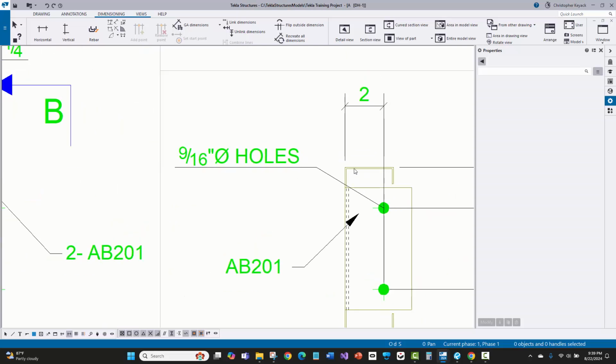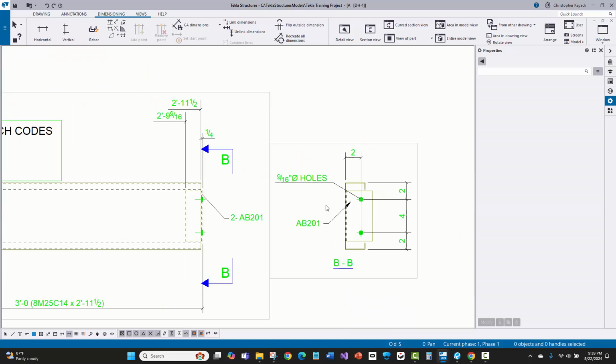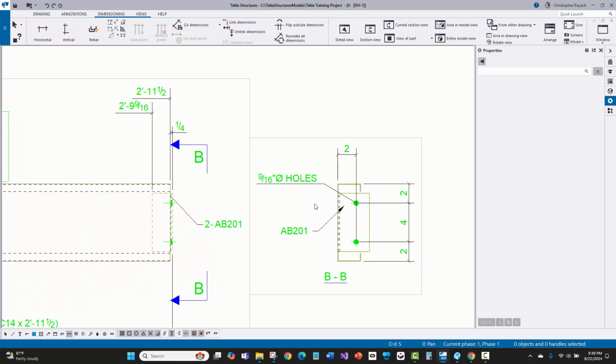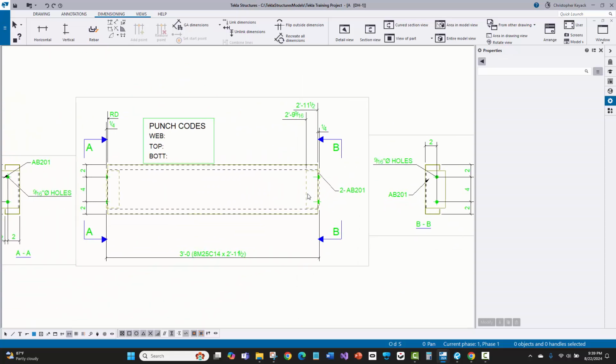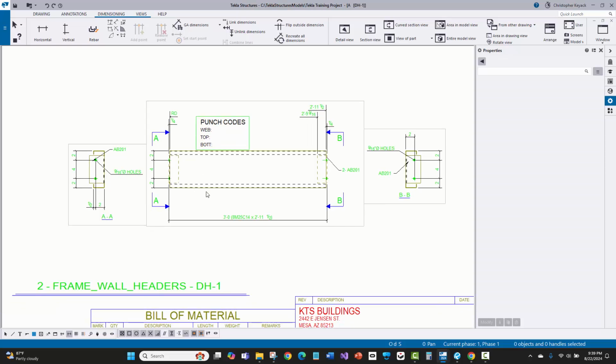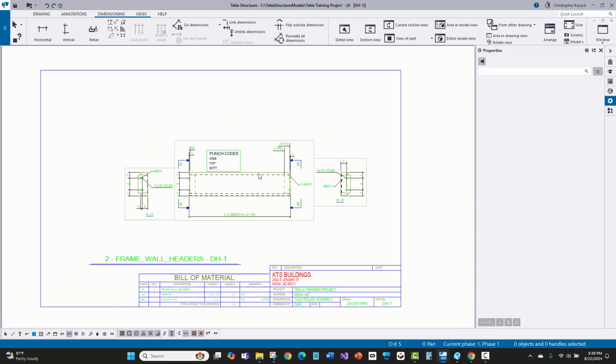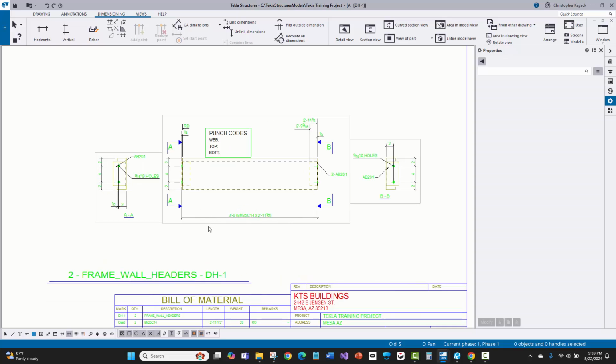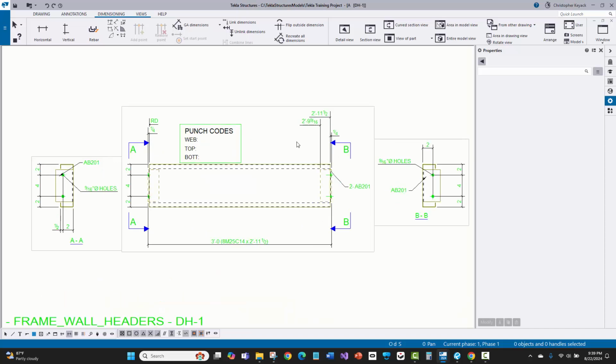And again, that's a little bit off because it is going to be a little bit more like 2 1/16 there in real life because of the gauge on the material. But basically, you get a feel for whatever dimensions and things you need to add. I do have the weld table and the welds turned off. I could turn them on, but this is gauge, so I just assume this is a simple standard weld covered by the weld standards, and that's why I don't have that shown here. But there you go, just a couple of minutes of adding additional dimensions.